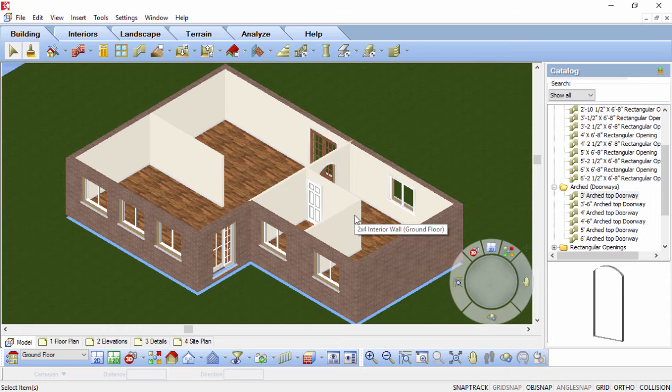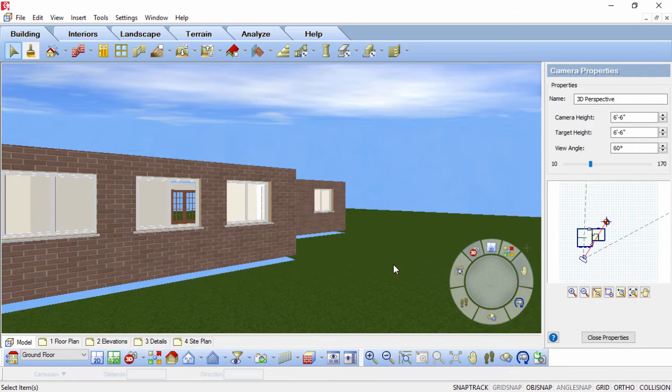The 3D Camera tool displays a 3D perspective view of your model, which you can adjust by controlling the view's camera. Interactive camera settings are displayed in the panel on the right side of the screen while the camera view is active. Select View, 3D Cameras, 3D Perspective, or click the 3D Cameras button on the View Control toolbar and select 3D Perspective. The 3D Camera button is also available on the Navigator. In a 3D perspective view, the scale of an element decreases according to its distance from the viewer, creating a more realistic view.